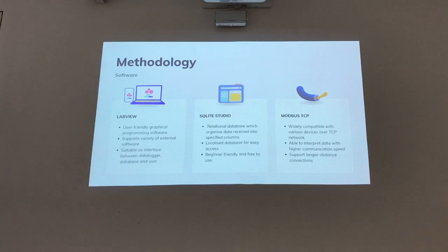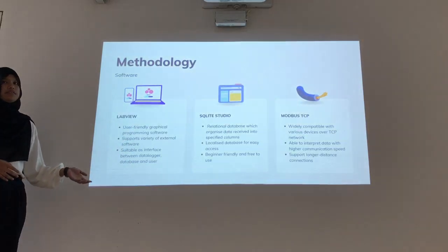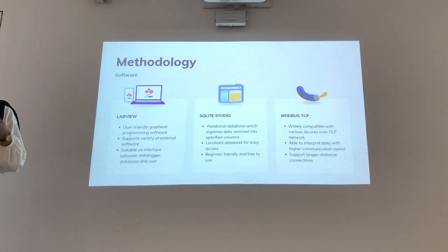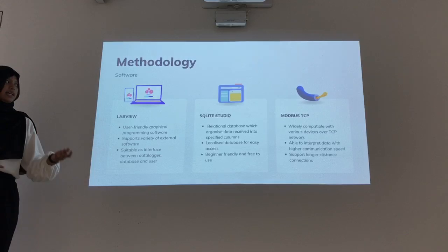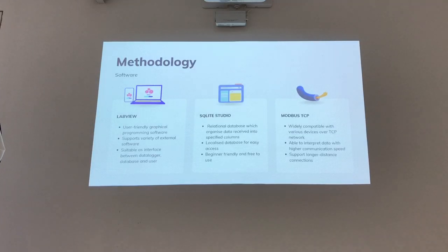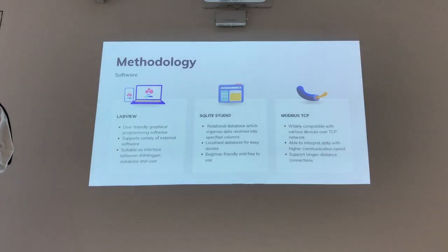Some of the methods that I'll be using are LabVIEW, SQLite Studio, and Modbus TCP. First of all, LabVIEW will be the main software that we use as the interface because it's very user-friendly and is able to connect between different types of software and devices. Next, our database will be using SQLite Studio. It's a relational database and it manages to collect the data and organize it into neat tables. And lastly, we have Modbus TCP. It will be the physical connection between the data logger and the computer. It's able to accurately interpret data, which is why I'll be using Modbus TCP.